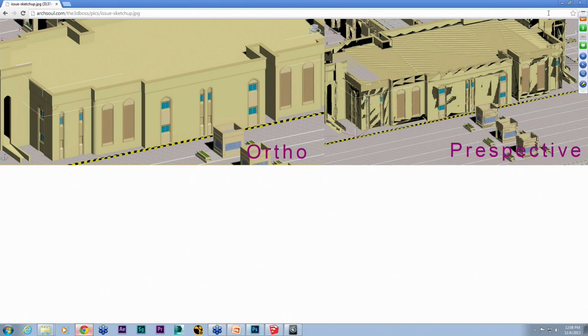Yeah, the suggestion here was backface cull in your object properties, so that might be another thing to check. But those would be the first and the last. So the default 2 lights would be one thing that you'd want to check, and backface cull. And then I would start looking to see if things have double geometry by selecting the mesh and pulling it forward and seeing if there's something at that same plane behind it.